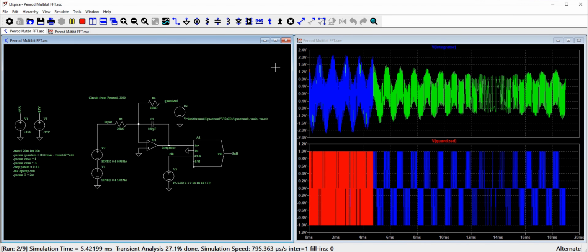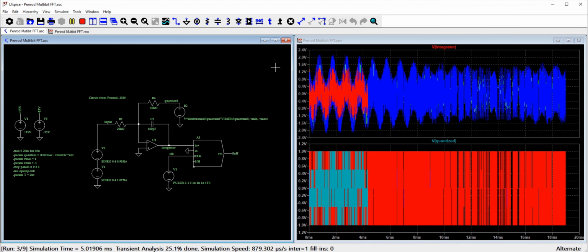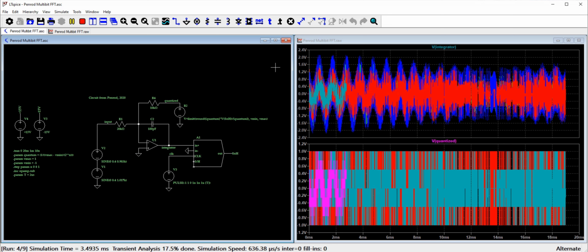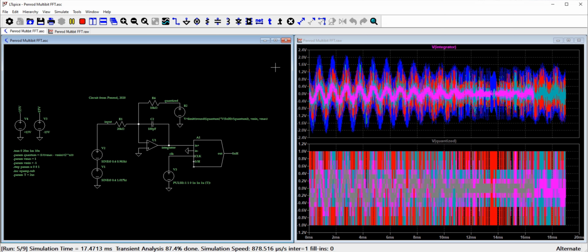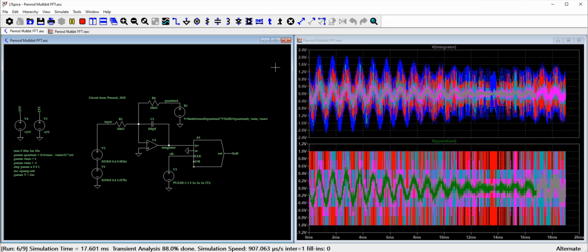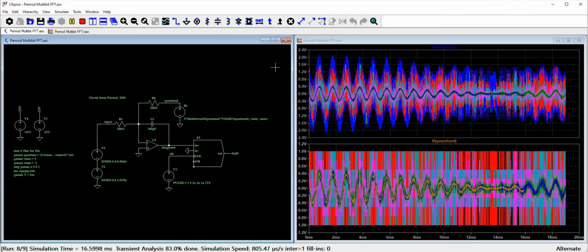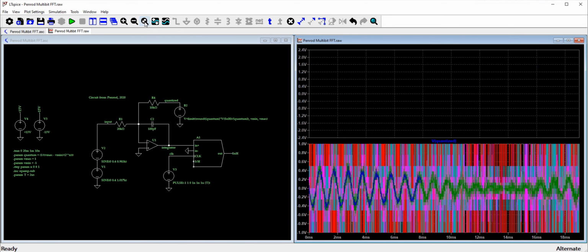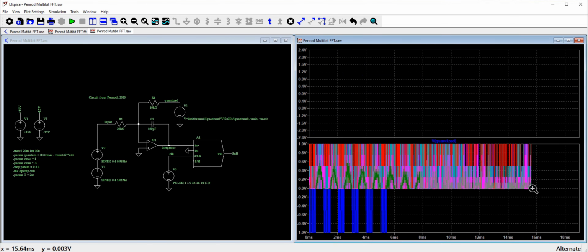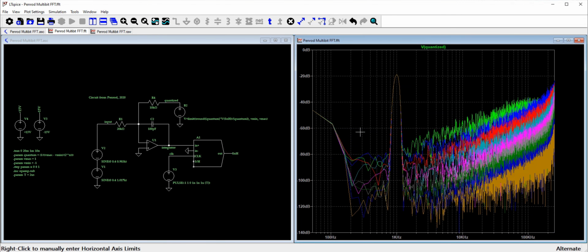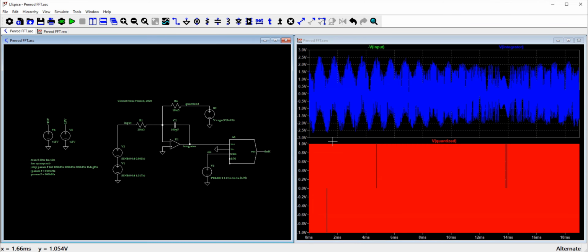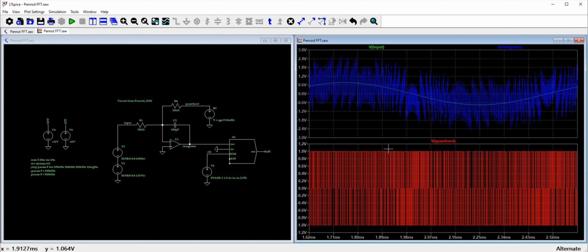By simulating a multi-bit quantizer using a behavioral voltage source, I can implement multi-bit feedback. It's interesting to see that as the number of bits increases, the output of the quantizer is more or less pulse code modulation with added noise-shaped dither that is generated by the modulator. The advantage of multi-bit quantizers is that high SQNR can be achieved without needing large oversampling ratios or a higher order modulator, the latter of which is impractical to implement in discrete analog but is much easier on the silicon level. The linearity of a delta sigma ADC ultimately depends on the feedback DAC.